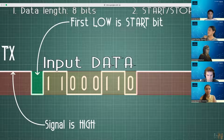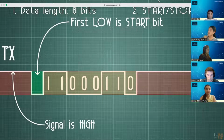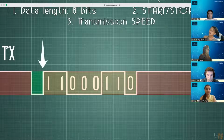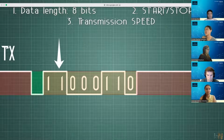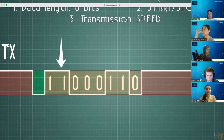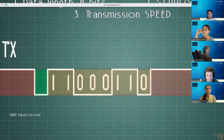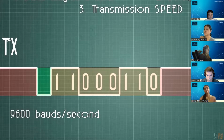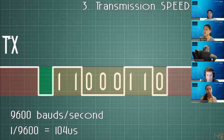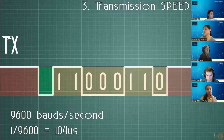And now here comes the third configuration, the speed of transmission. Without knowing the speed, the receiver won't be able to know when one bit will end and the other one will start, and by that it will read the wrong value. For that, we need to set the speed in bauds per second. A very common UART speed is 9600 bauds per second. That means that the length of the bit will be 1 divided by 9600, and that equals 104 microseconds.